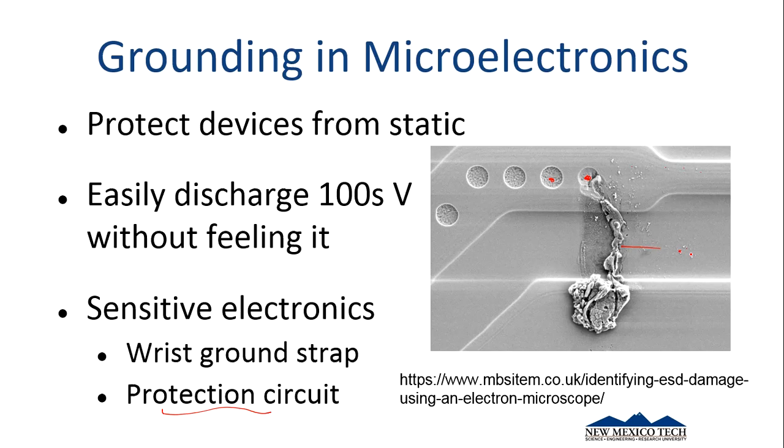So the bottom line is, when you handle sensitive microelectronics, sensitive instrumentation equipment, whatever, you need to have a ground strap. This is also true if you ever go to work in energetics. Many a chemist has made flash powder and accidentally set it off early because of a static discharge. So that's something you've just got to watch out for. You've got to have a way to ground out any charges you develop on your hands.